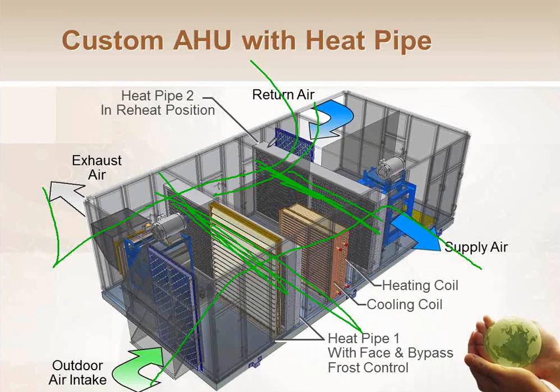So we can use some of these ERV technologies not just for treating my outside air, but I can use it for some reheat after my cooling coil. I grab some energy, some heat I should say, bring it over to this side of the airstream, and then after my air has been cooled by my cooling coil, I'm going to help reheat it back up to an acceptable temperature. So I can subcool it for dehumidification reasons and reheat it for free over here, or near free. This ERV pipe over here is for energy recovery on my outside air. Whatever energy is left, I can use to precondition it.